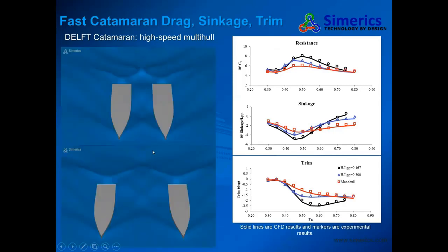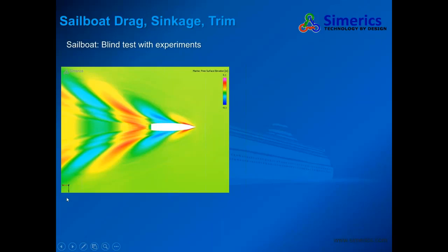And with our VOF method, here we're using the HRIC, which is a high resolution interface capturing algorithm. With this algorithm, we can successfully capture all the detailed features of the waves. We see how the waves interact with each other in the inner region, and you see how different they are with the two different separations. So that's for the catamaran.